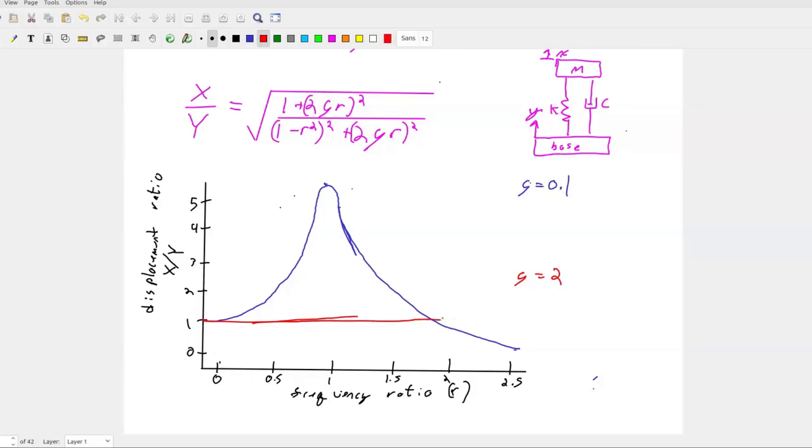And maybe I just drop down just a bit. I don't ever go above 1, right? This means if I have a metal rod, and I put in 1 millimeter of displacement at one side, what do I get out at the other side? 1 millimeter, right? And it doesn't matter the ratio of what that natural frequency is. I'm pretty much always going to get out of it what I put in, which makes sense.